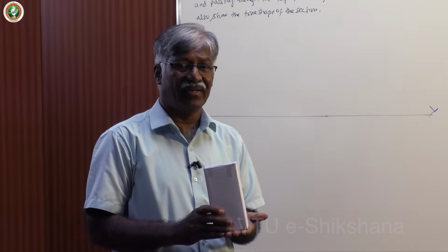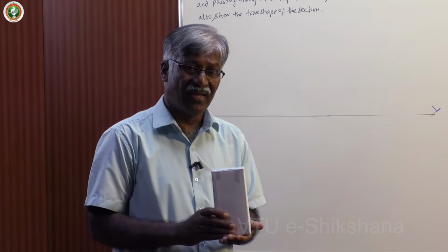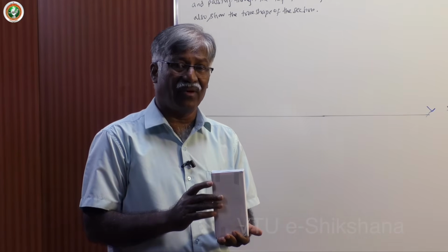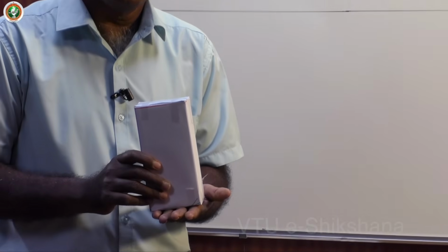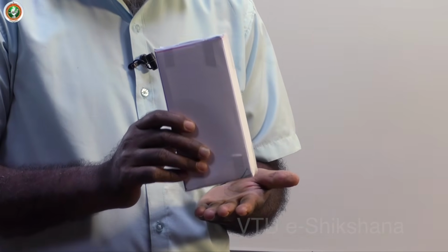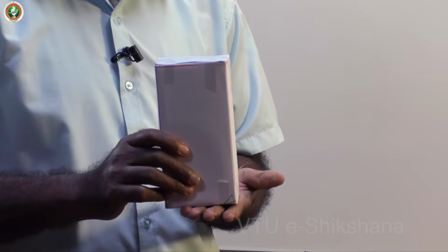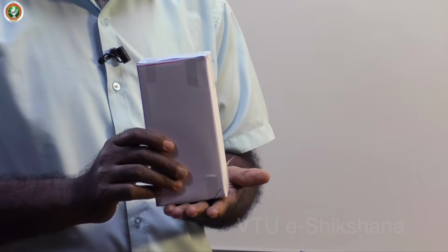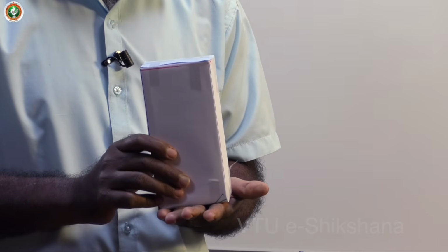We keep that particular prism or pyramid on its base and discuss the development of the surfaces. Here let me discuss the position of the solids which is on ground, having its base on the ground. That orientation is important here, rather than inclination to axis. No inclination to axis, but orientation of the base surface which is on ground is very important.